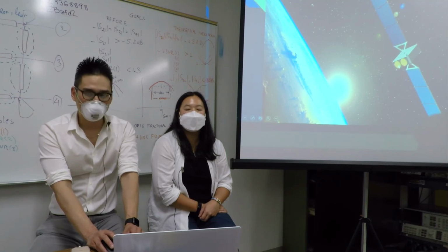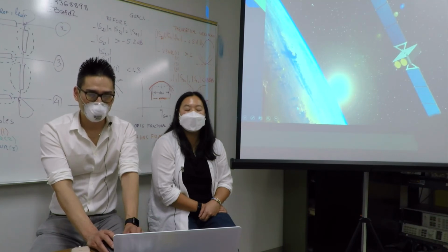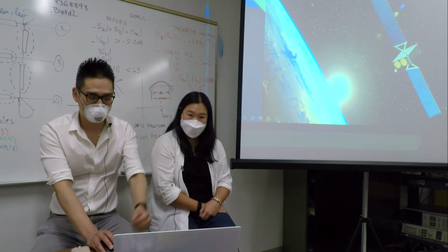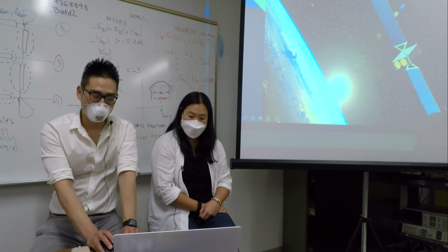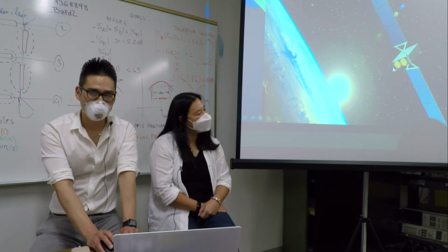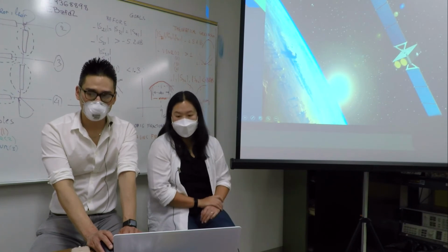Now, the problem with that is, what is the key parameter that gives that amplifier the appropriate performance? Because we've got all these signals hanging around in space, all this stuff that we don't want going into the satellite, and that potentially gives rise to noise. Noise, and of course from the satellite itself. So the type of amplifier designed in that case is called a low noise amplifier, which has its own art in terms of designing. The LNA, the first device after the antenna, is responsible for boosting that signal and giving it enough signal to operate.